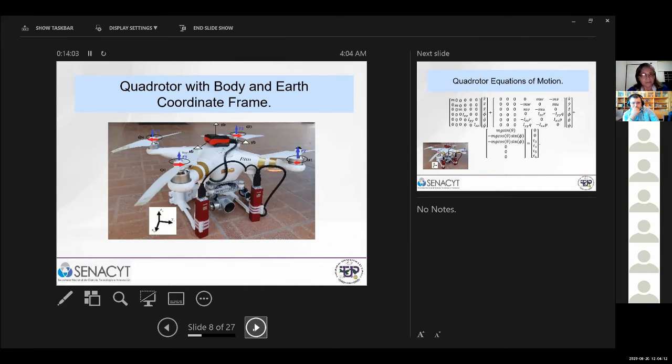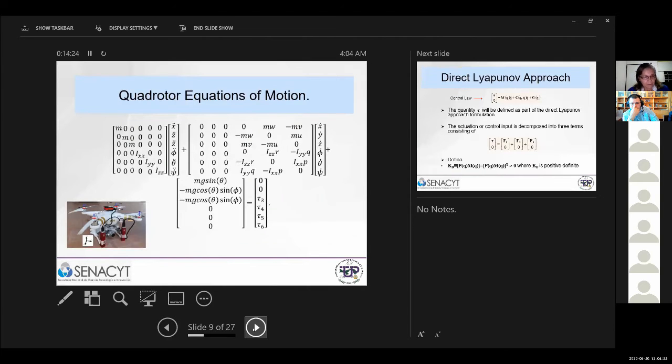Here the system geometry of the quadrotor together with the dynamics equations of motion are presented. A quadrotor has 6 degrees of freedom and only 4 actuators. Its mechanism is modeled in a cross configuration with symmetrical arms. This system is underactuated because the external generalized forces are not able to accelerate its states in all directions.